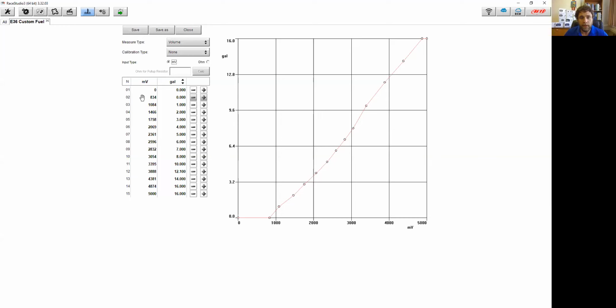And the way they set this up was they started to take the values, and I'm guessing here, they probably started the car empty and they added a gallon of gas. And then they took a millivolt value reading, right? So when they added a gallon, it jumped to 1084. And Roger did tell me this part, he said what they also did is they ran the car with a gallon in it until it wouldn't run anymore. And they found it was 834 millivolts, and they put that in as 0. So when the dash read 0 is when the car shut off. It wouldn't run anymore.